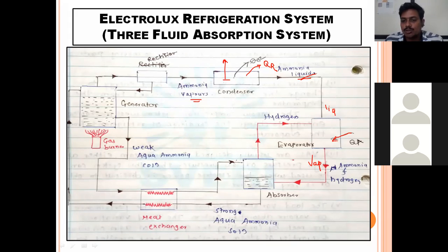So here, in case of the evaporator, we require to convert liquid refrigerant into vapor refrigerant easily. And for easy conversion of liquid refrigerant into vapor refrigerant, we require to reduce the pressure, because at lower pressure the boiling point temperature of that refrigerant will also go on decreasing. So that was the main purpose of providing higher pressure to the condenser side and lower pressure to the evaporator side.